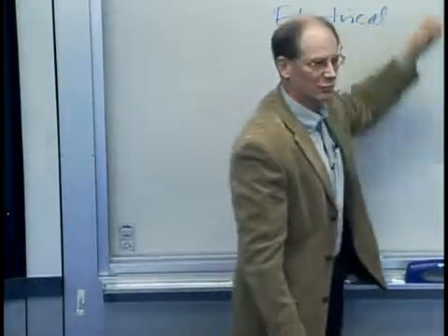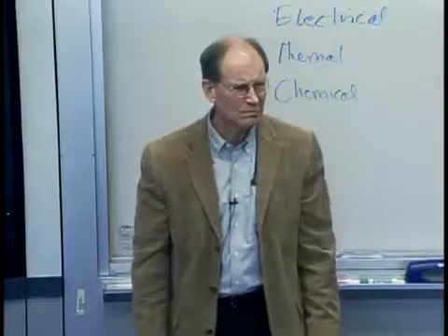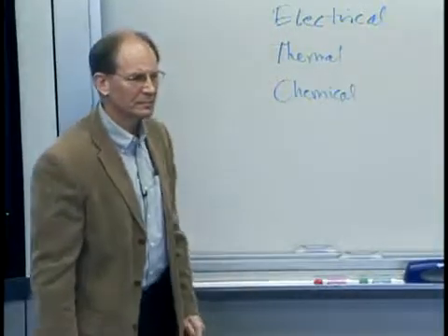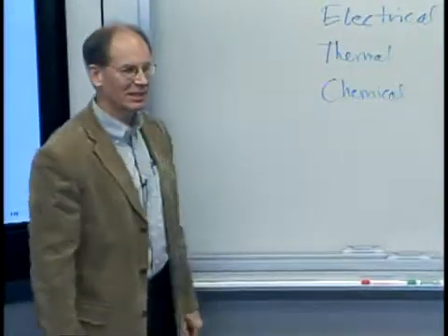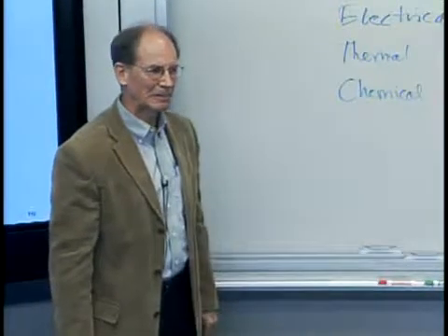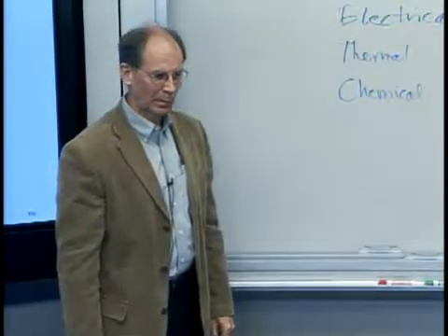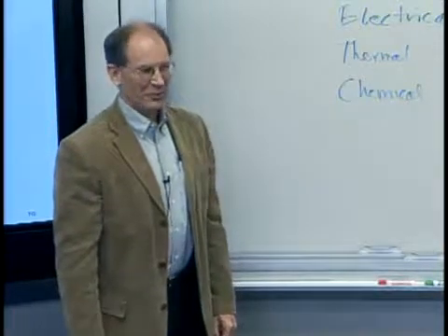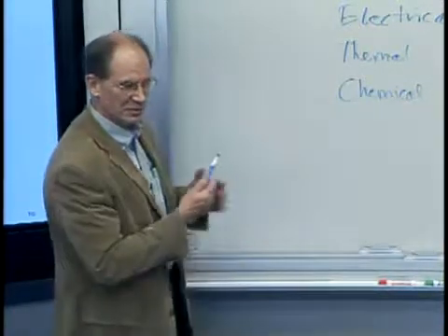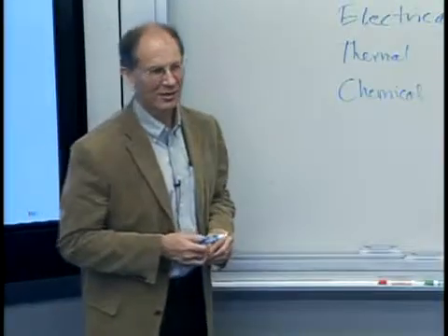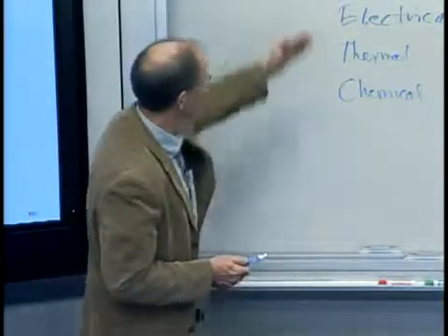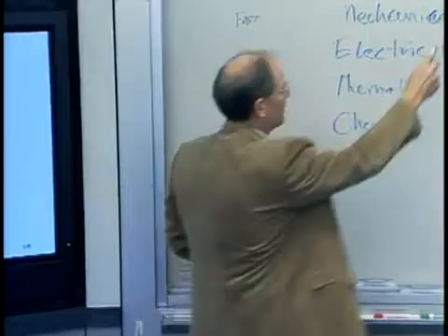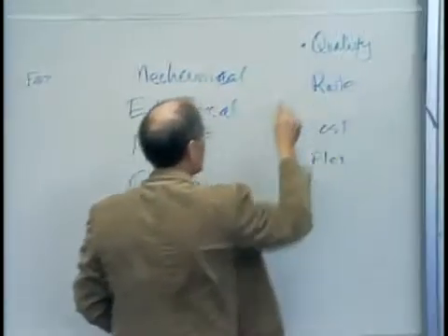That's rate. What about quality? Tolerances are also side effects of the process. Like what side effects? Say a little bit more about side effects. Well, you've got the theoretical, maybe I want to cut a perfect square, but the tool's not going to cut perfectly square edges. So depending on what process I use, it may have undercutting or rounded edges. Absolutely, absolutely.